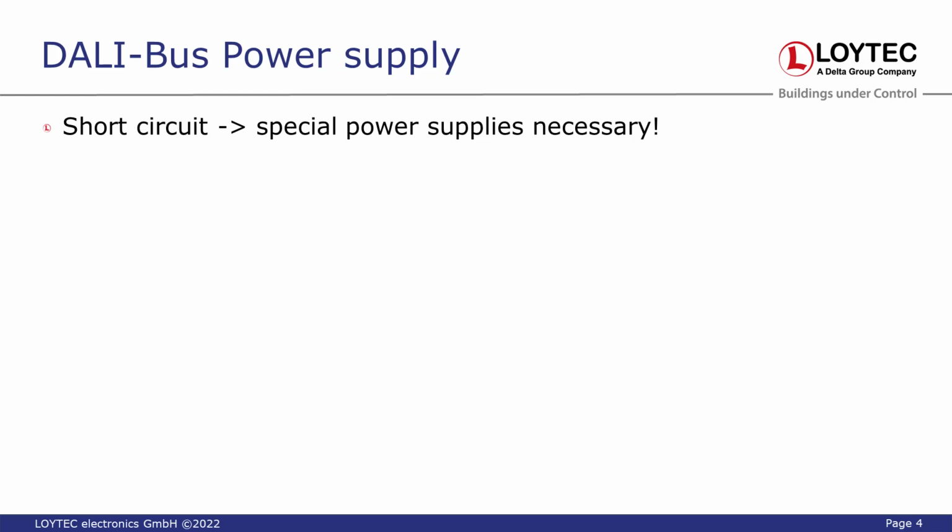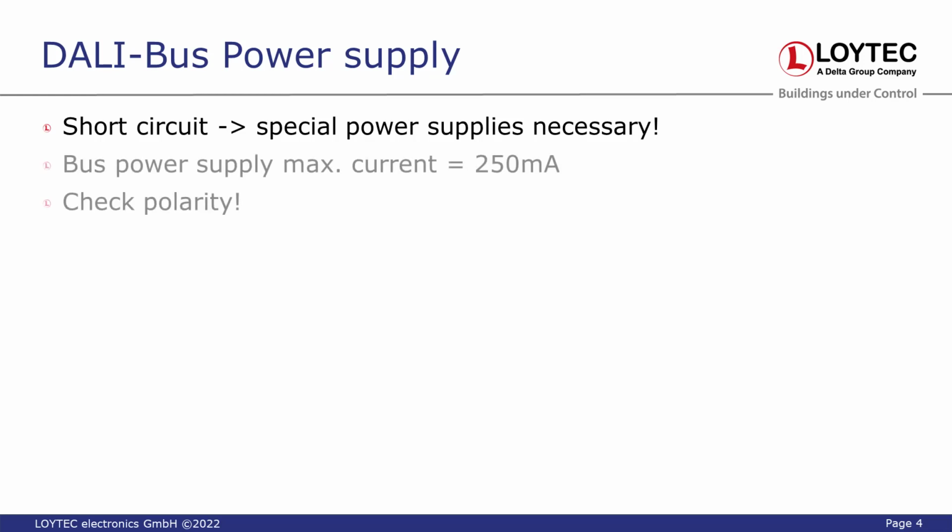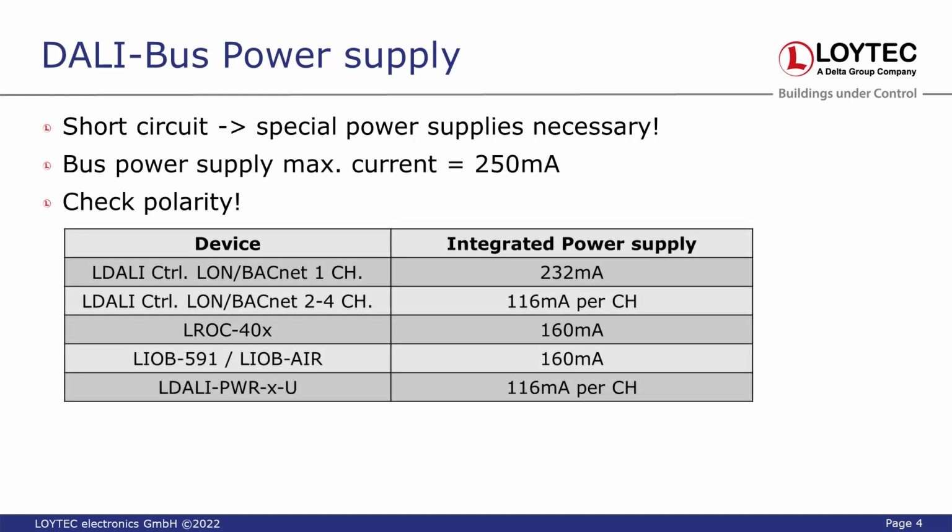Multiple DALI power supplies can be used, though the total supply of a DALI channel mustn't exceed 250 milliamperes. Otherwise, damages to the transceiver of the attached DALI device may be possible. Most of our DALI-compatible controllers offer an integrated DALI power supply. The max supplied power can be seen in this table.